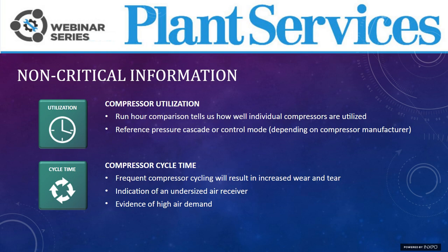Compressor cycle time is also a very good gauge and indicator if you experience frequent compressor cycling, that eventually can result in wear and tear, and can be a good indication to see if your station is well designed or not.